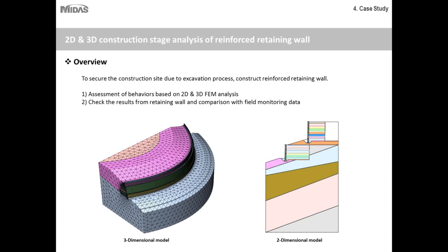So why did they need 3D and 2D analysis models? As I mentioned in the very beginning, sometimes your reinforcement layout varies along the length, or if your section is varying along the length, then you need to move one step ahead of 2D analysis, which is 3D analysis. And as you can see, this is not a regular structure, it is a continuous, changing structure.